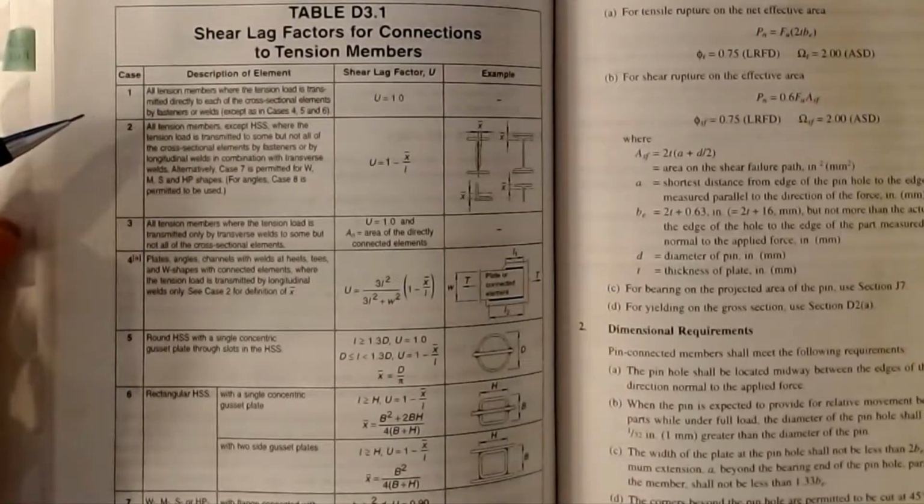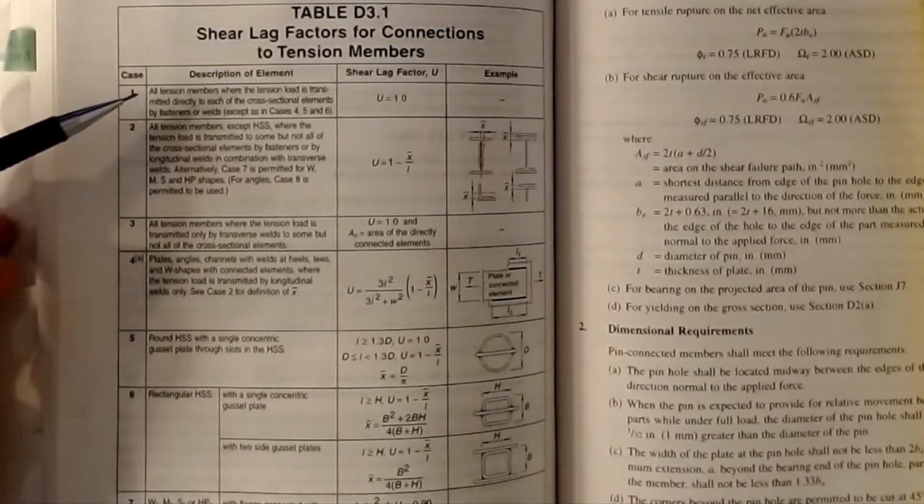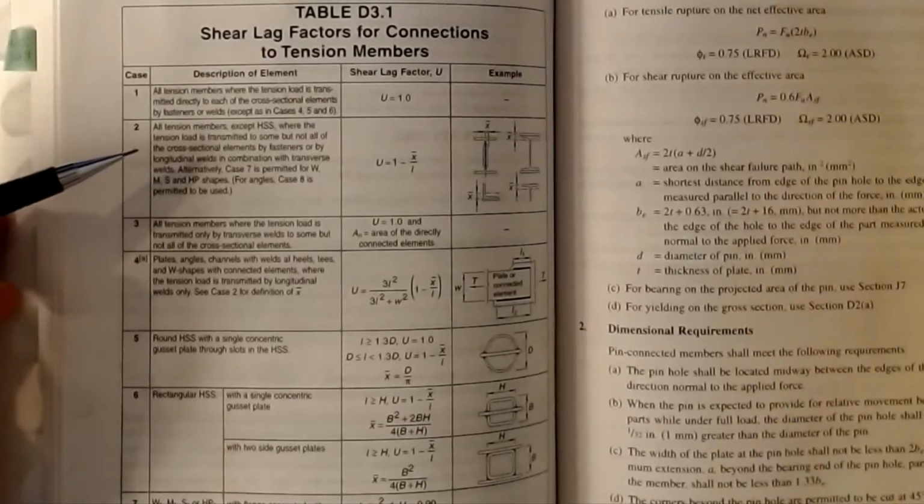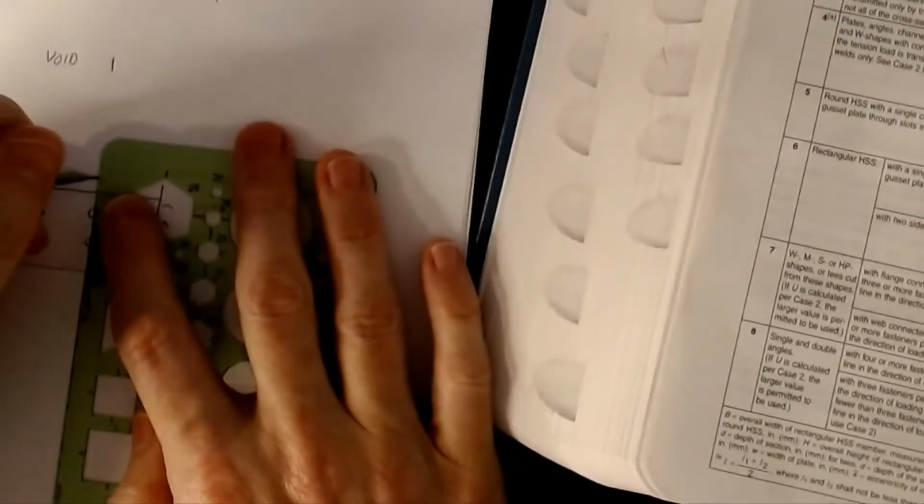In the case of shear lag and the flow of those forces that we talked about in the last video, if our section has enough bolts in it that it's reasonable to say that the entire cross-section is being loaded, that's typically a case like a flat plate. So if I just real quickly sketch this, it's a flat plate, and we play our flow net game, and I put 2 bolts across this section, and I load this, and this connection is long enough. Well, it's possible that my effective area, as I start to trace that boundary line like we did in the last video, if this is my net fracture plane at this location, then it's safe to say that it's pretty much fully effective. This is a U of 1.0.